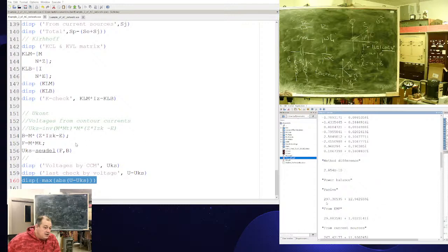Power balance. Dissipated power, 297 watts of heat, plus, what's this? The imaginary part. It's the amount of energy swapping forward and backward. From all this, if you need to pay for this, here you pay the tariff. It's what the meter accounts. And this part, if you take it from the network, for small customers it's free of charge, for large customers, 1/10 of the tariff.